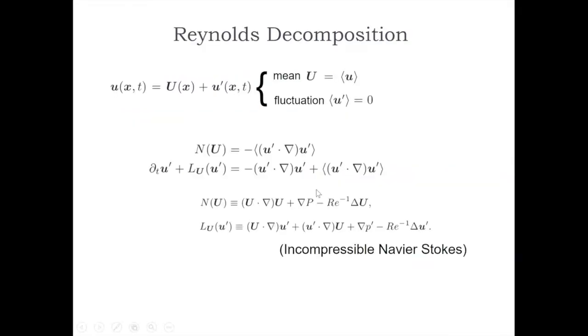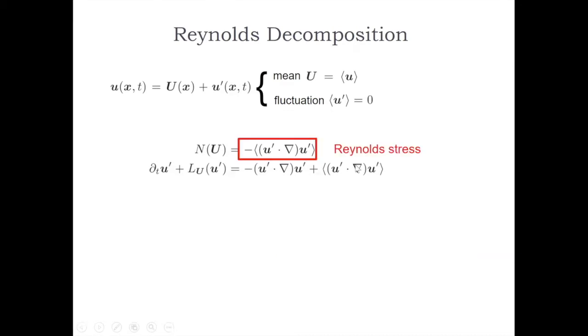Anyways, so I start as usual from the Reynolds decomposition. I recognize here this equation, which is the equation for the mean state, and I recognize the fluctuation equation. And so what I'm going to do is that I'm going to keep this Reynolds stress interaction in the mean state. So that's a time average of the Reynolds stresses. In that case, it's a time average, but I could use the phase average, like we said, or a spatial average. And then I'm going to use the linearized dynamics, but around that mean state, not around the base state. That's the main difference.